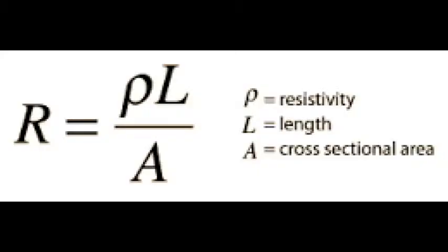To solve this example, we're going to have to know that the volume is always constant, and that the volume is equal to the area times the length. So if the length L doubles, then the cross-sectional area A is halved because they are inversely proportional. And therefore, given the equation for resistance and resistivity from example 18.3, we can see that the resistance is going to increase by a factor of 4.